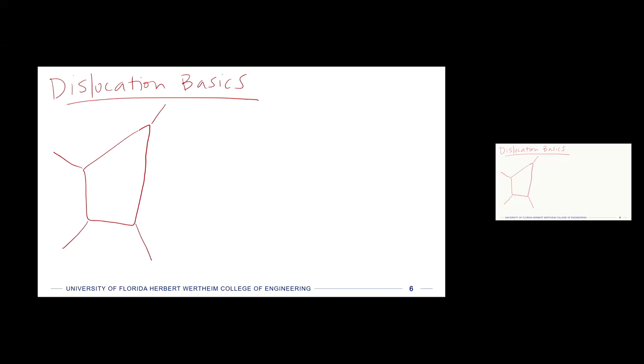And so what happens when you zoom in, if you use some kind of microscopy, is that you see slip bands in the grain. So I'm going to draw them in a different color. And you see them clustered together. But if the grain has the same crystal orientation, which is kind of the definition of a grain, then all of the bands you see will go the same angle, right?